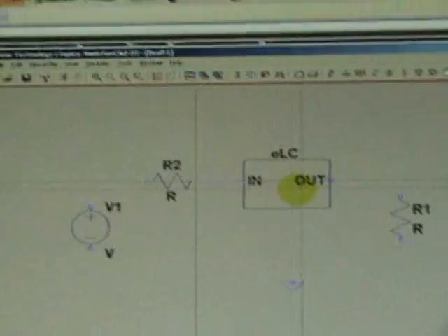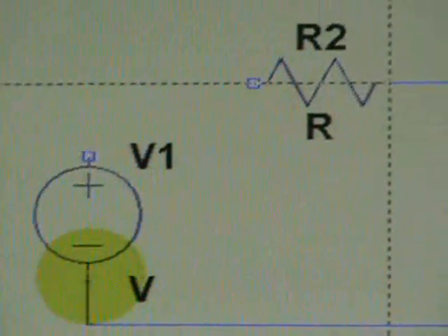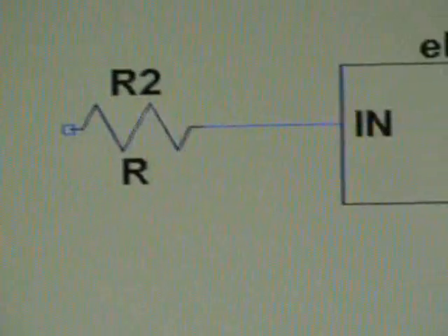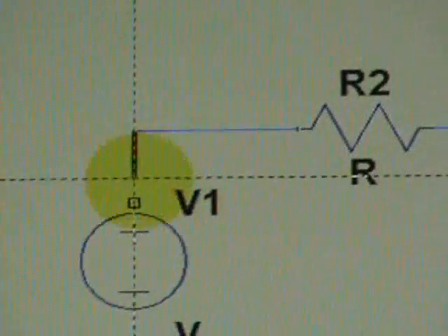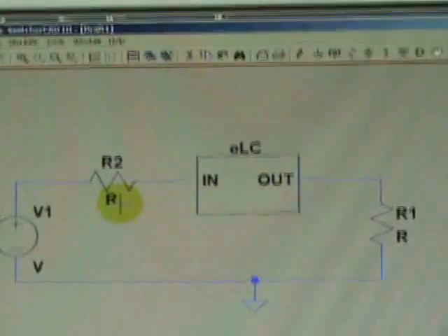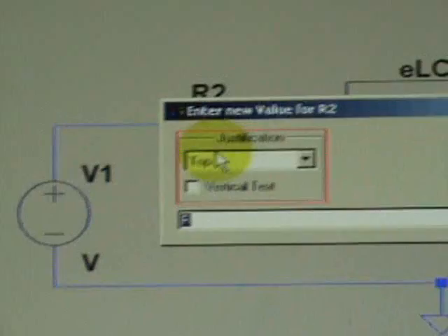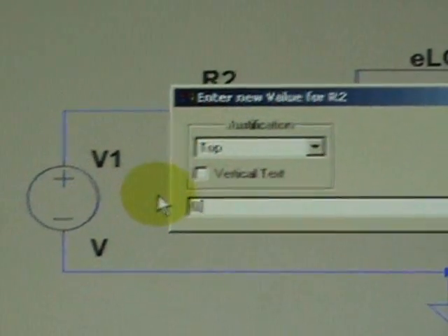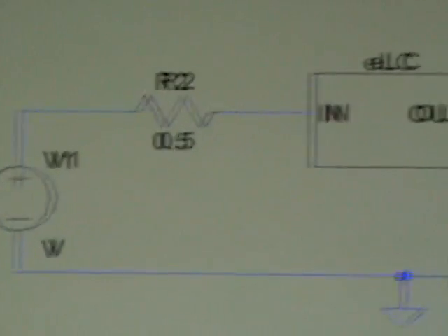Now let us complete the wiring by picking this tool. Click to the next, click to the next one, click, go all the way, go up, click, hit escape key, go back to the pen, click. We might as well complete this. Click, hit escape key. Now to change the value of the resistor, left click. Remember we call that 0.5 ohm or any value. And I believe, right click, I believe we call that as 1 kilo ohm resistor.